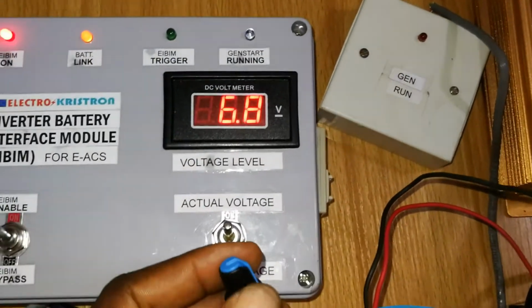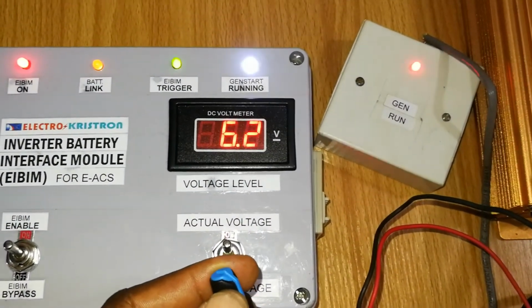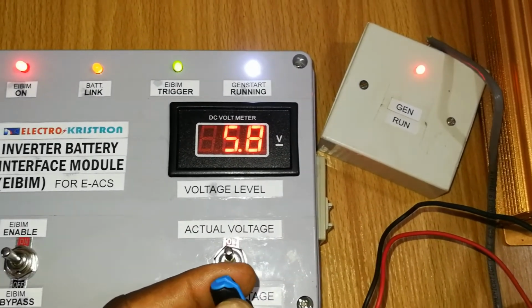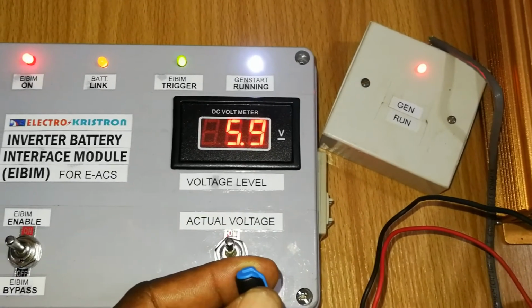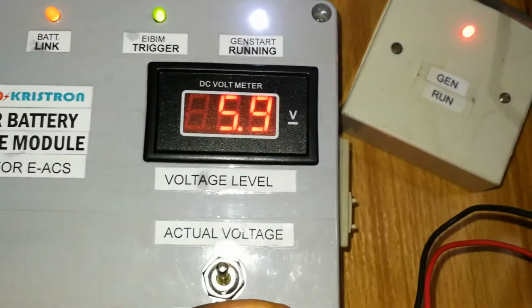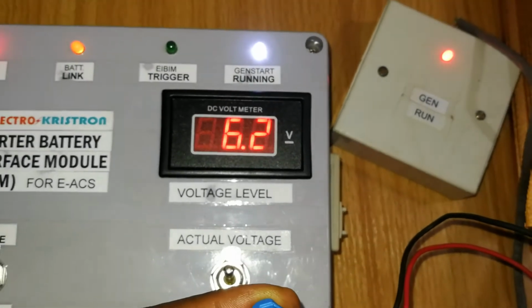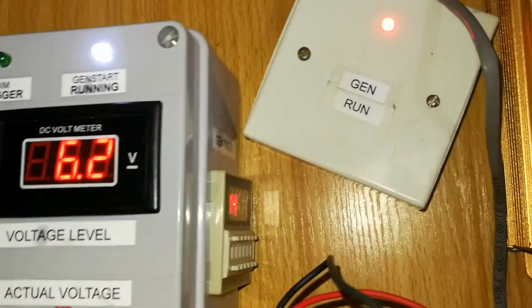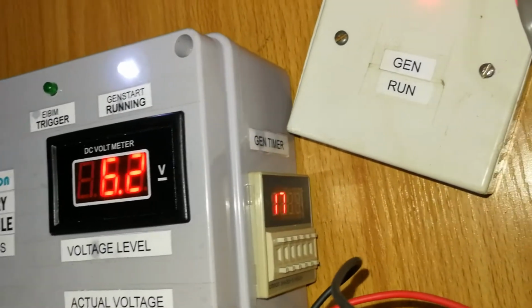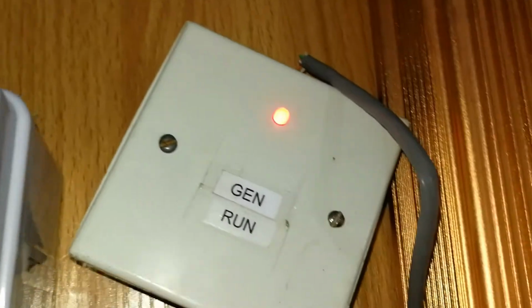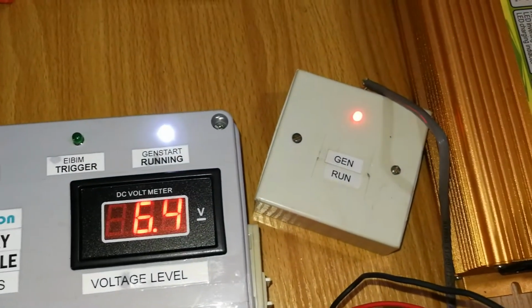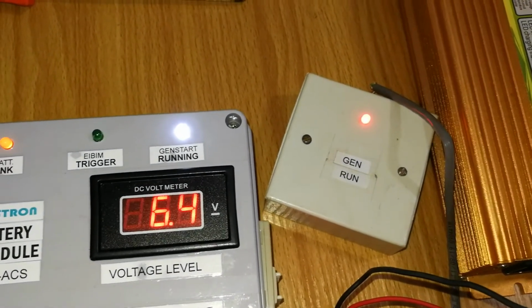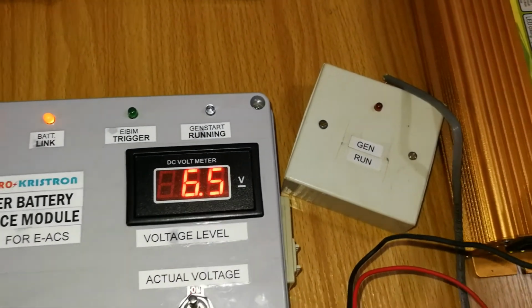Okay, so let's take that again. Battery low, system comes on, and then as the batteries are getting charged through the generator or whatever other means, the voltage increases and then the light goes off. The white light remains because the timer is still counting. Immediately the counting is complete, the white light goes off, and likewise your gen run signal on the ATS too is disengaged and the gen stops. Okay, fine.